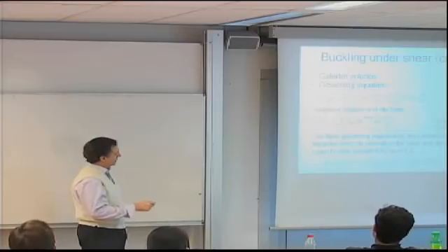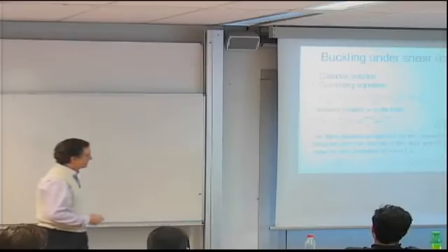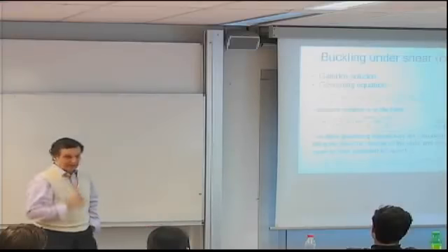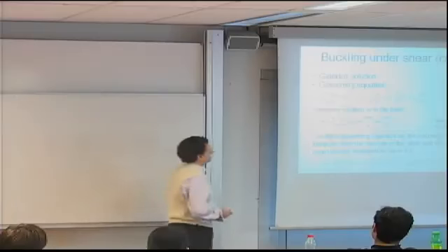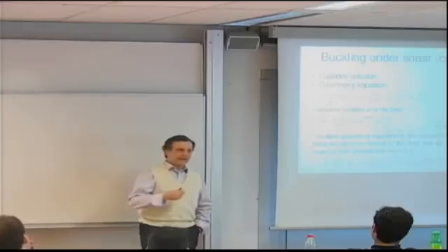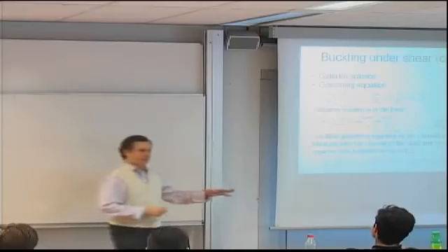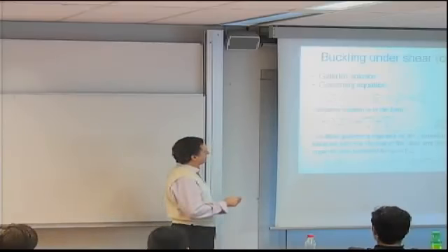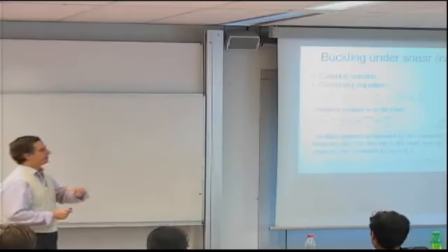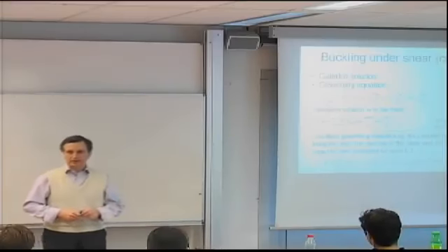Remember the whole thing, minus 2nxy. There's my minus 2nxy because I brought it all to the left-hand side. Substitute in my governing equation, shown at the integrand here. Then multiply that, and that was the genius of Galerkin, multiply that by orthogonal functions. And then integrate over the entire domain you're trying to solve the problem. Set the result equal to 0, and if you solve now for the unknown coefficients, a and n, those unknown coefficients that you will find will be the best you can ever hope to get for this assumption. So if you make this assumption, then the a and n will actually be the best you can get.